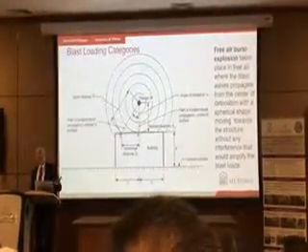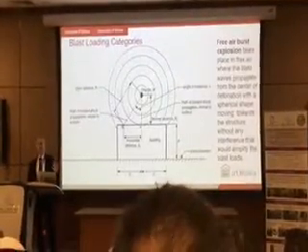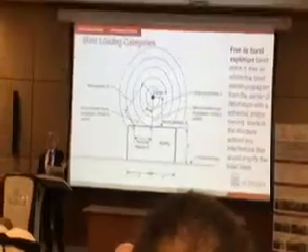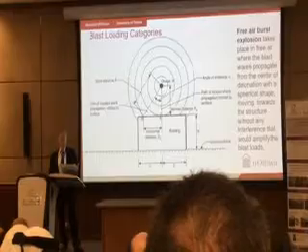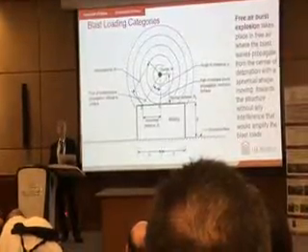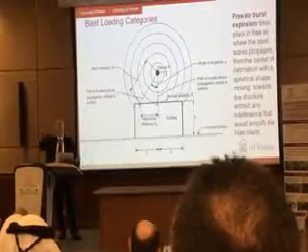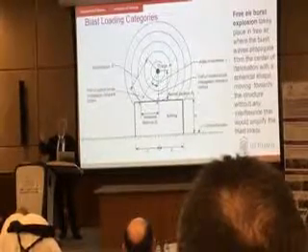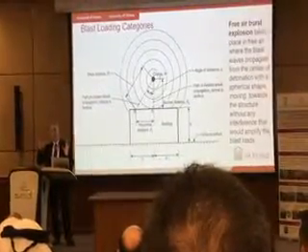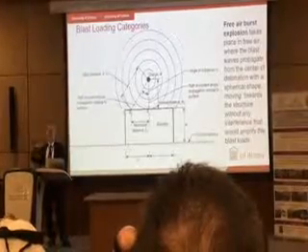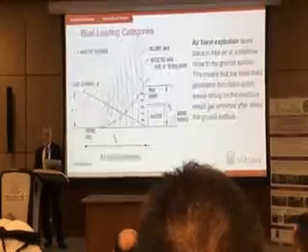So, having covered the basics, now we will look at loads on the structure. There are 3 or 4 types of explosions as they relate to location. First of all, if it's a free air burst, let's say it's dropped by an airplane or something exploding up in the air, it causes spherical shock waves. And these spherical shock waves go and hit the building. This is one category, and the movement and the expansion of the shock wave is spherical in nature.